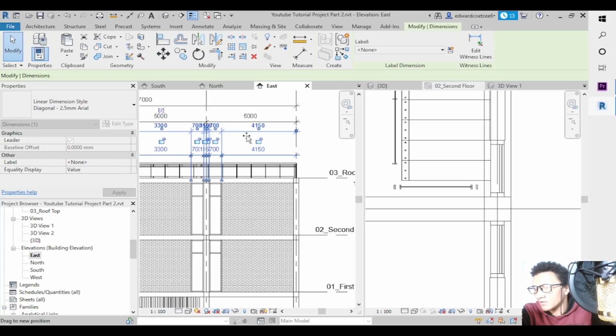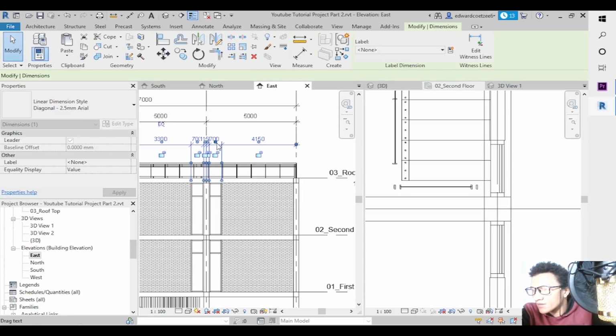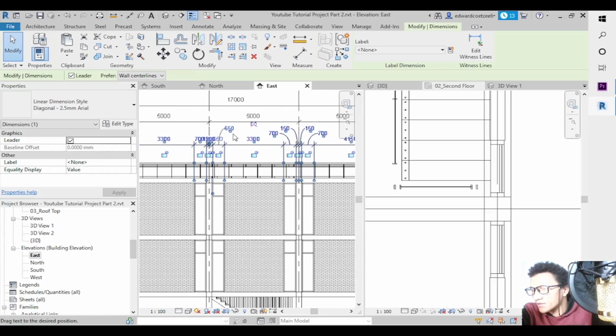But if from the start I wanted them to cast the bolts into the concrete, then you have to do the dimensions at the same time as the drawings, because you don't want to get to site and then realize that your contractor didn't.